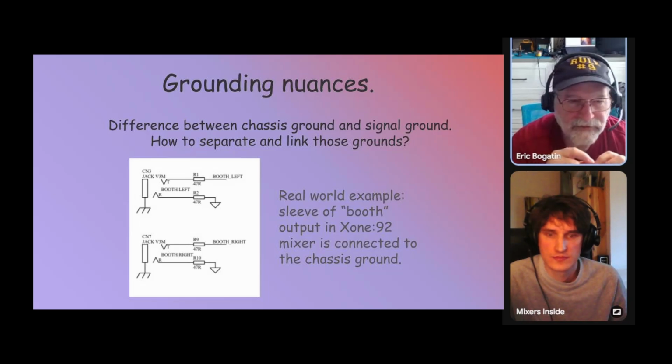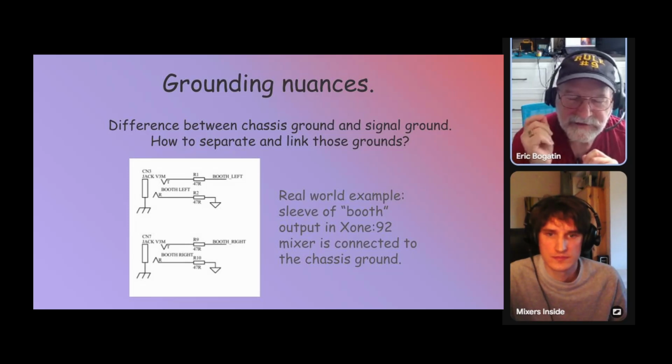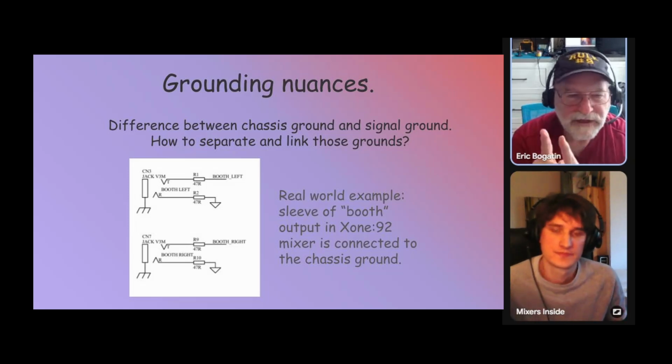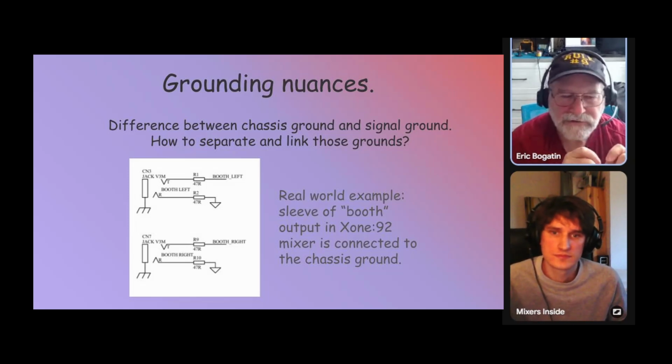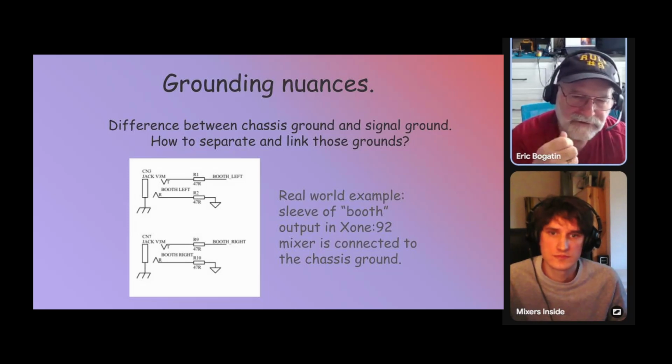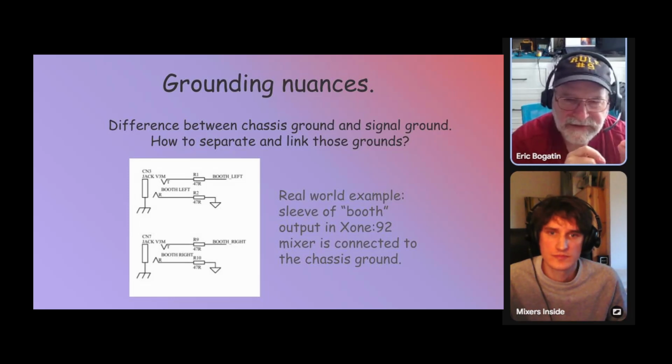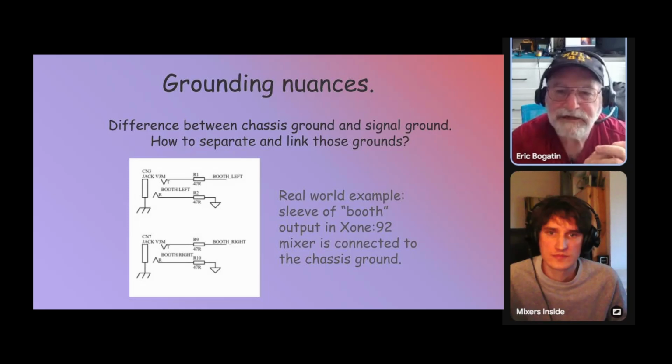If you think about the voltage coming from the microphone, for example, there's a sensor there that's generating a small signal. It's a differential signal between the signal and its return. That return is the coax, and now that goes back to the shell of the jack that gets plugged into the chassis. And so you still have the voltage between the signal and the chassis inside your box.